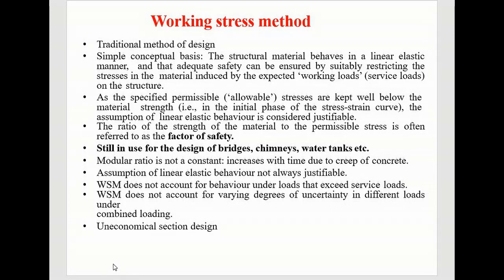This method was also called the load factor method. Here the ultimate load is considered for the design, and for the design the load factor is taken into consideration. Sorry, I said factor load, it's not a factor load, it's a load factor. The formula for this is: load factor is equal to ultimate load divided by service load.